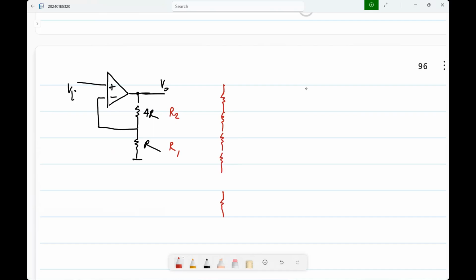So now can you think of some dynamic technique for this? What can you do? You can basically swap between them. One possibility is you just rotate between them. That is, you have 5 resistors. In the first cycle, R5 is R and R1, 2, 3, 4 make 4R. In the next cycle, maybe you make this R4 and 1, 2, 3, 5. There are many ways in which you can choose. You can just choose randomly, in a pseudo random way, or you can just rotate through the elements